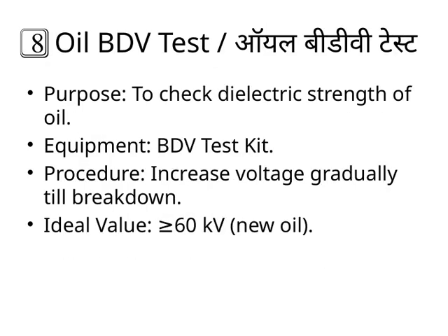Let's talk about the oil BDV test, known in Hindi as oil BDV test. The main purpose of this test is to check the dielectric strength of the oil. Essentially, we want to see how well the oil can resist electrical breakdown.